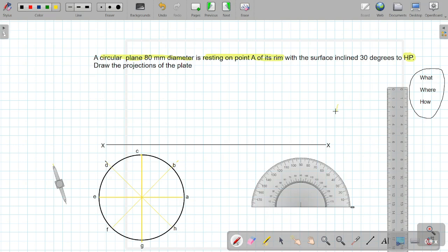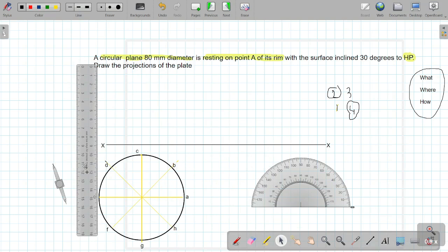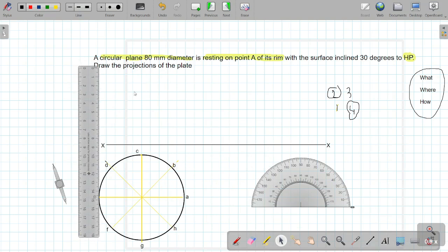Now after step 1, I will write as usual. Step 1 is made below the XY line. Then comes step 2, which will be made just above step 1, then step 3 and step 4. Out of which step 2 and step 4 are made by means of projections. So I will now complete step 2 by means of projections. Projection should be taken from each and every point.